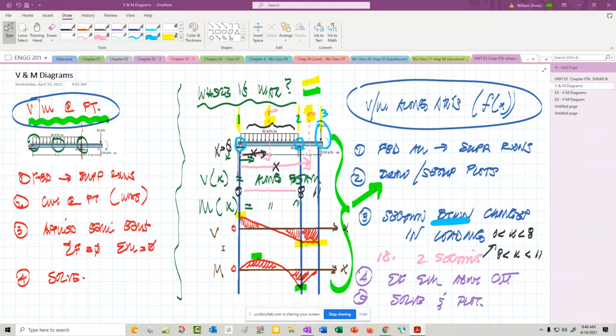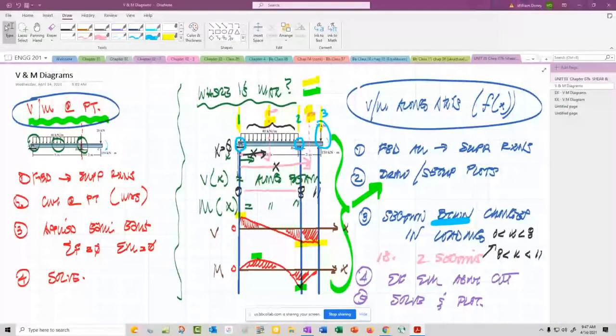Now, why are we only doing shear and bending moment? What about the normal? Where did the normal go that we were dealing with last time? Well, again, beams are designed to support vertical loading. Not so much concern about things perpendicular, so we normally don't consider that in analysis. And with the load being applied vertically, the horizontal axial load really doesn't come into play. Said another way, a beam's resistance to shear and bending is more important in the design of the beam than its resistance to axial loading. That's really what we're looking at.